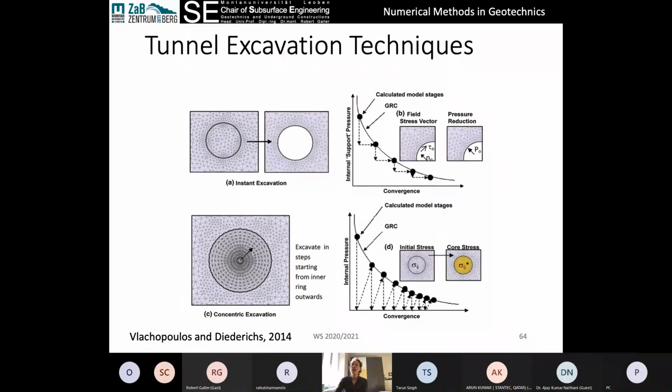First is by modeling our excavation using a pressure. The initial condition would be that the pressure here, or let's look at it over here, the pressure here is the same as the in situ stress out here. Right, so that would be our initial condition. Everything is in balance, the stresses haven't changed. We have an excavation, but the rock mass is represented by a pressure. And if we slowly reduce that pressure in steps, so we reduce the pressure, calculate the convergence, reduce the pressure, calculate the convergence, reduce the pressure, calculate the convergence, we can get an approximate solution to this ground reaction curve.